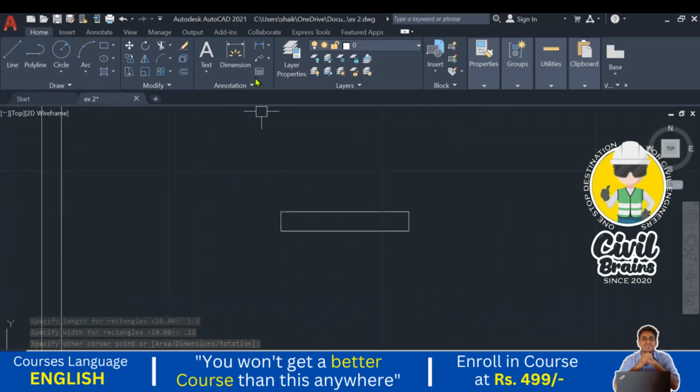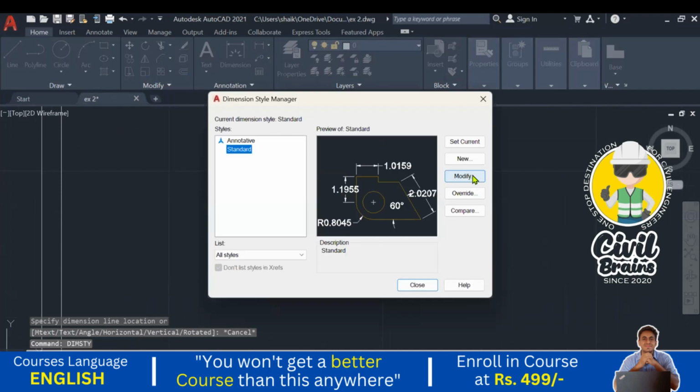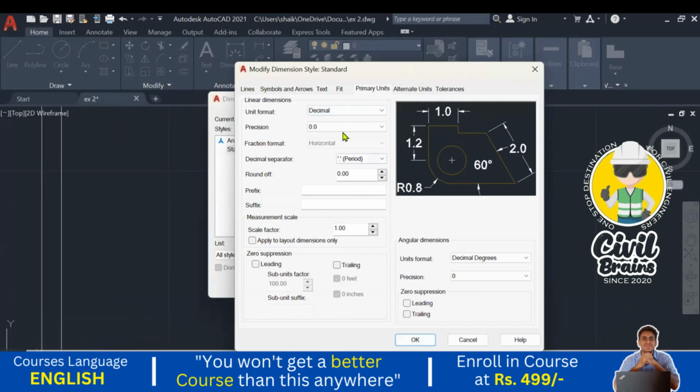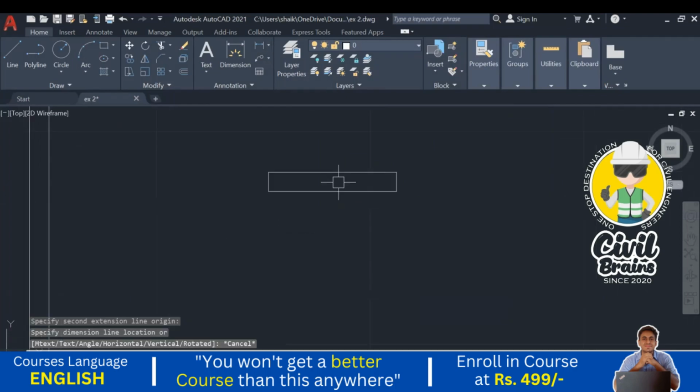Okay, so here our window is ready. So this is our window. What is the size? 1.5 meter. Here you can see this. Why is it showing this much? Dim style. I just go to dim style, modify, primary units, 0.00 we can consider. Okay. So 1.5 meter and 0.23. Correct. So this is our window.